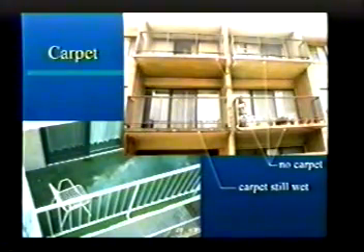This is a slide I like to show to condominiums when I argue why carpet is bad on the top surface of balconies. And in this slide, this is really the slide that I like to use, you see the 4 balconies. Now this particular photo was taken 24 hours after it stopped raining. These 3 balconies have no carpet, and this one does. And you can see coming out of the edge of the balcony, the water is still oozing out. Water is being forced into that concrete.